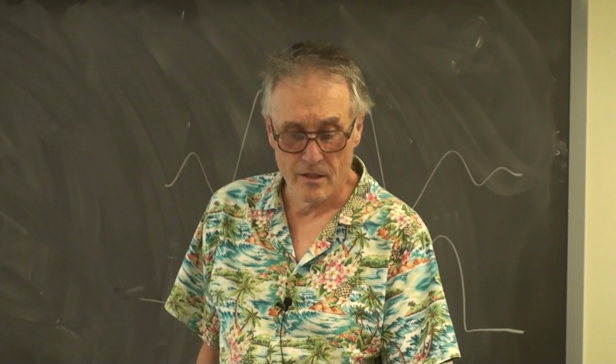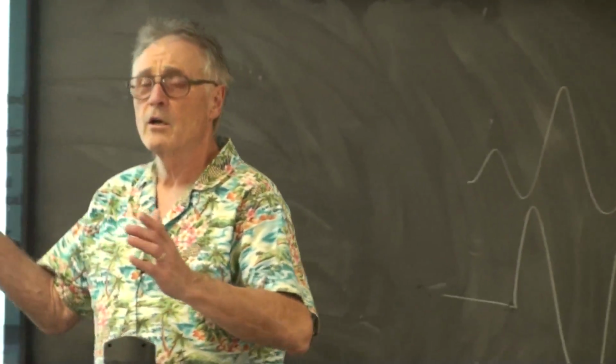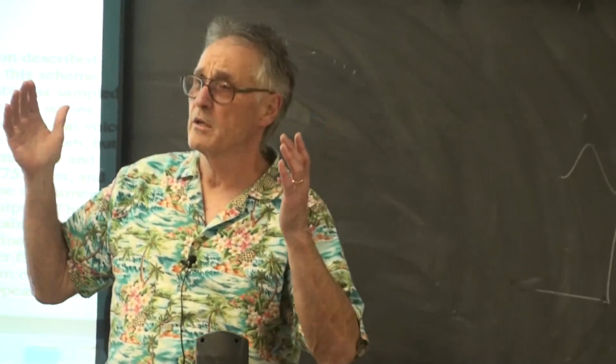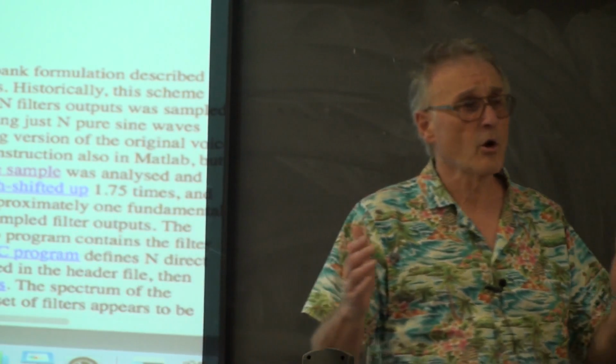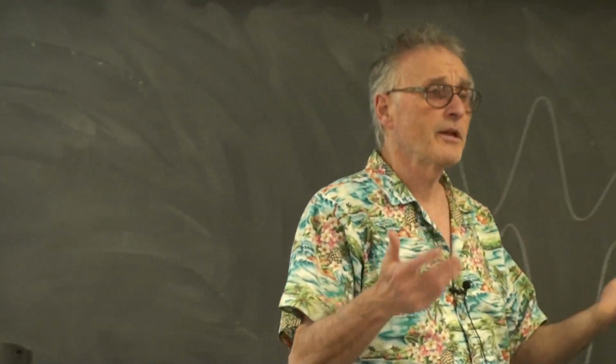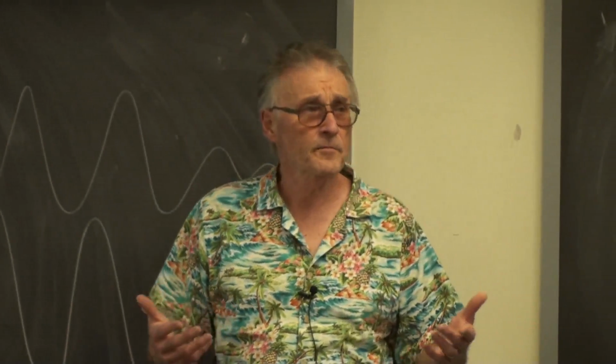Now here is, if we take 30 log-spaced frequency analyzer channels, so these are second order filters, logarithmically center frequency spaced across 340 hertz to 3400 hertz. We record the average amplitude output of each one of these filters for 18 or 20 milliseconds.